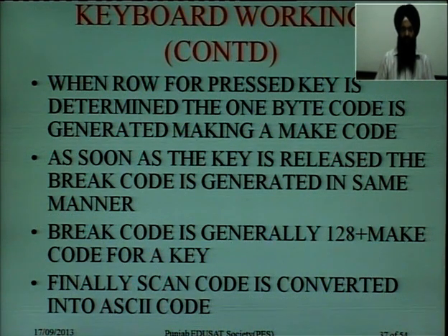Because the make code is unique for each key, the break code is also unique, by adding 128 plus the make code for a key. And finally, the scan code is converted into ASCII code, and then it is given as input to the computer.